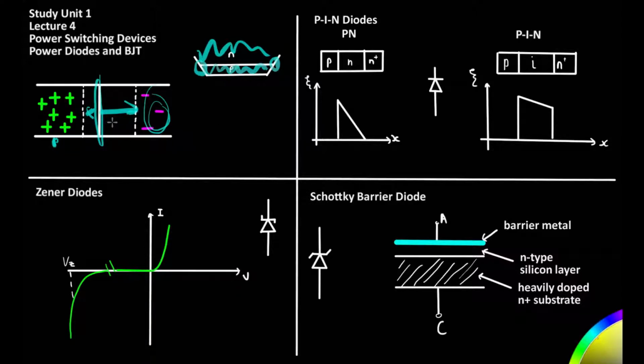The speed at which the diode switches is determined by the lifetime of carriers through the space charge layer. In other words, the longer the lifetime of an electron or carrier through this region over here, the longer it will take the diode to switch, because once the polarity around the diode has changed, the lifetime of that carrier must first be expended before a charge will stop flowing. One way of improving, or rather decreasing, the carrier lifetime is to introduce gold or platinum into this neutral region, so that these atoms provide absorption centers for the carriers, thus reducing carrier lifetime.